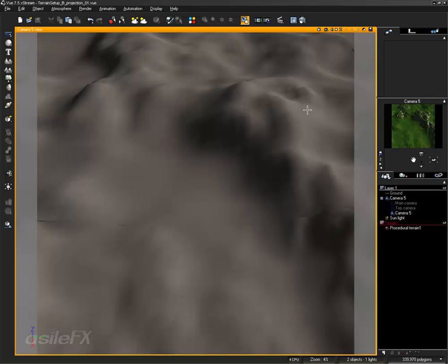Same thing with the content in ecosystems. If you need to get the file maybe off your network into another system, or you're sending it to a render farm, something where that content is not going to be available, then use the compress options and the incorporation of texture maps. But otherwise, if you're doing that for every single scene, it's going to take forever to save, and you're going to end up with a ridiculous amount of file sizes. So definitely stay away from that.